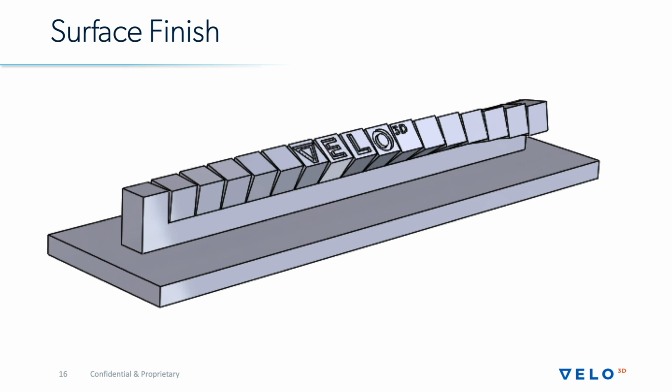All right, I'll touch on surface finish. This again is something that I don't like to give a single number for, exactly because it depends much on the minimum thickness specs that I gave. It depends on the angle that you're printing at, or the angle that your surface is at. The geometry that we often use is this CAD you're seeing right here. These are roughly 10 millimeter square blocks that are tilted at different angles. And it goes from what we'll call 90 degrees or vertical on the far left all the way down to a 10 degree down facing surface on the right.